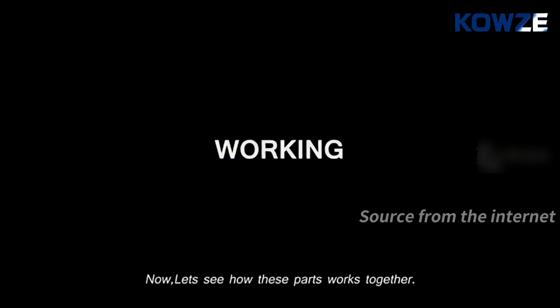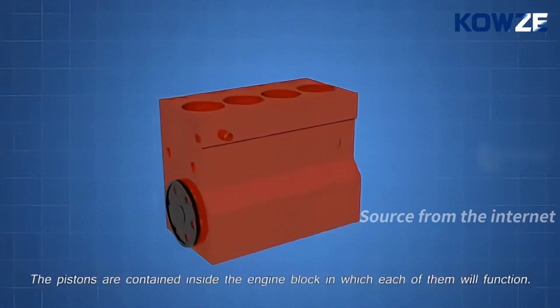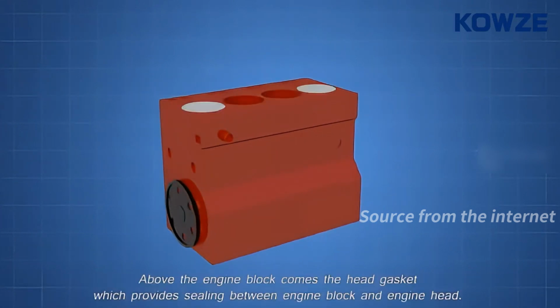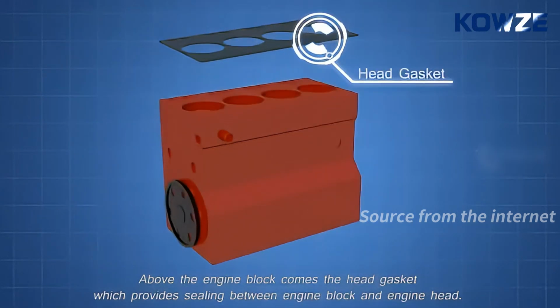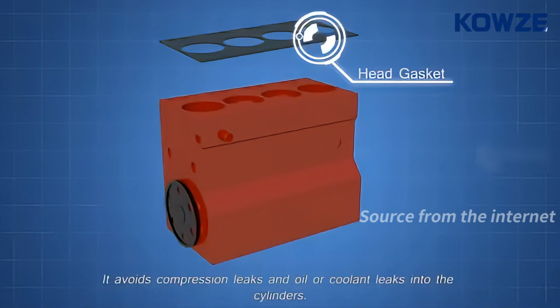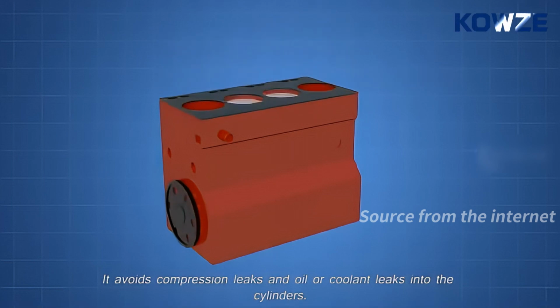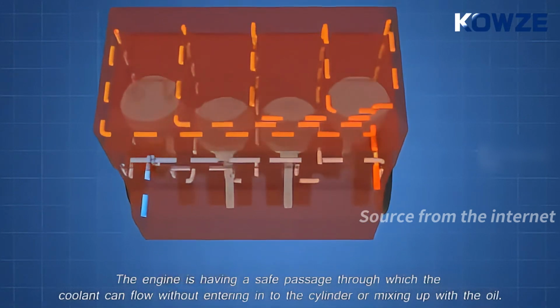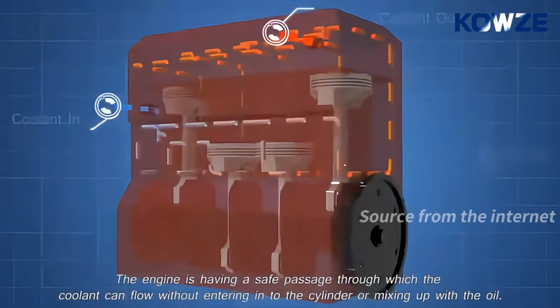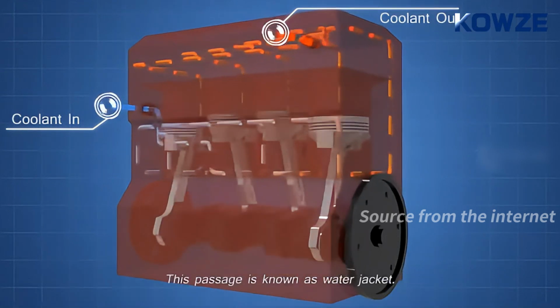Now, let's see how these parts work together. The pistons are contained inside the engine block, in which each of them will function. Above the engine block comes the head gasket, which provides sealing between engine block and engine head. It avoids compression leaks and oil or coolant leaks into the cylinders. Above that comes the engine head. The engine head has a safe passage through which the coolant can flow without entering into the cylinder or mixing up with the oil. This passage is known as water jacket.